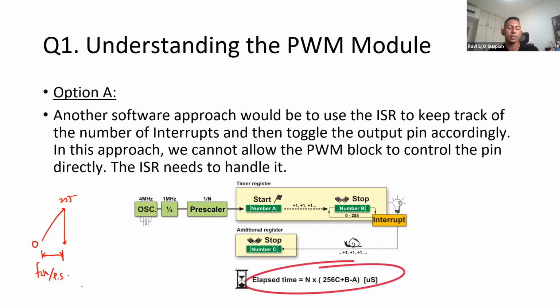That determines how long it takes to count from 0 to 255. Now I want this to be longer, which means I do not want to overflow and increment my count right now. So what I can do is use this event to generate an interrupt, and in the interrupt I have another variable that I increment. I can maybe call it tick, plus.